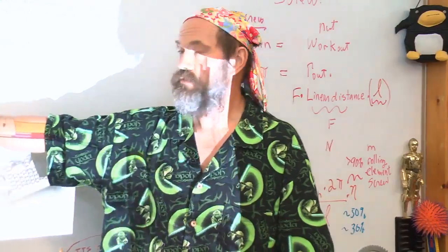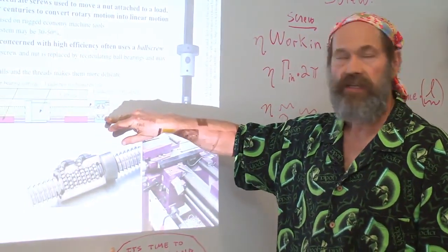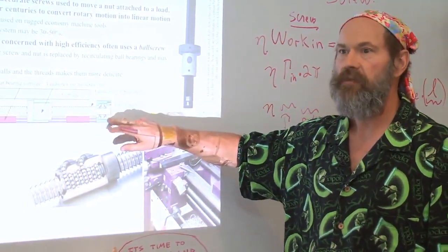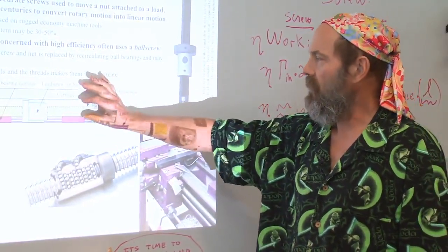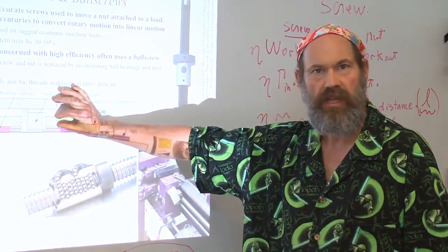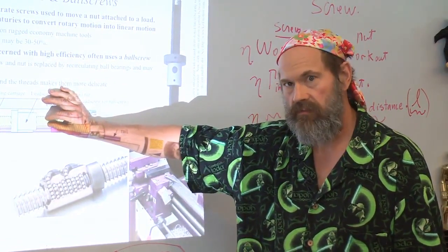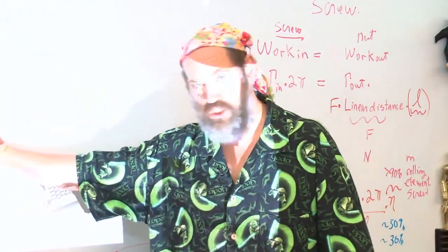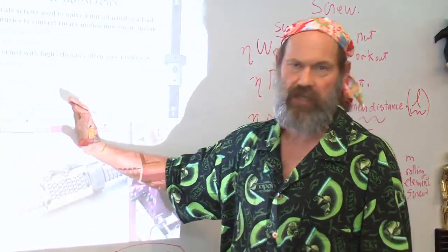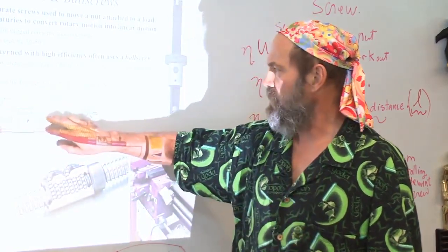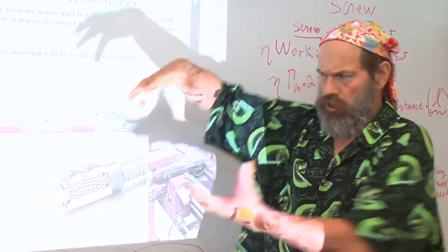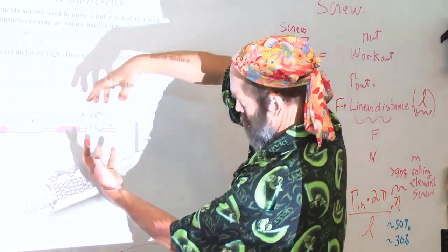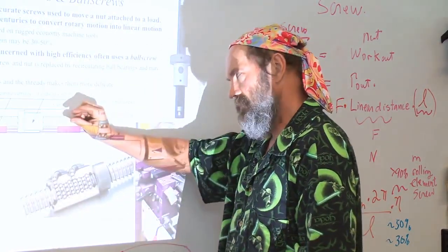What is the stiffness of the screw shaft? If I just said I want to make this a very high-speed system, why do I want to make the screw shaft as small diameter as possible? Why not get a really stiff machine tool carriage that can just cut really heavy loads? Don't I make this shaft big and strong? Why do I want to have a small diameter?